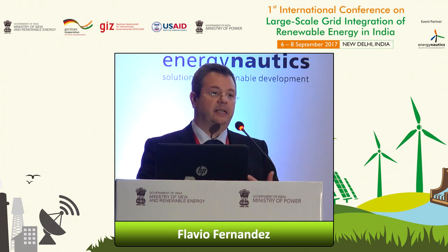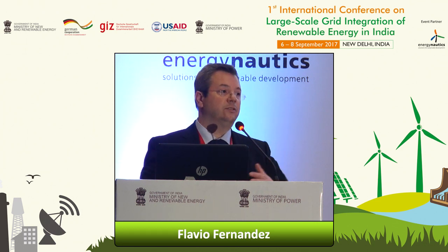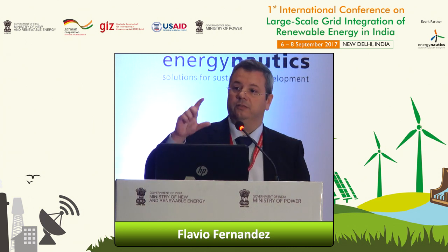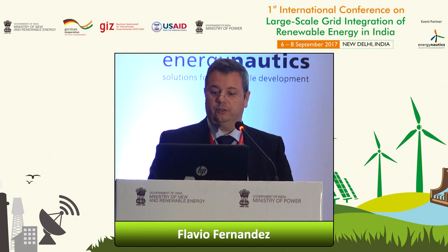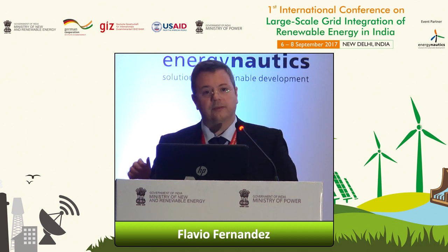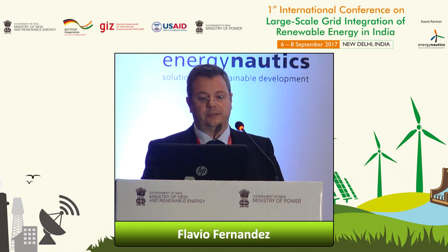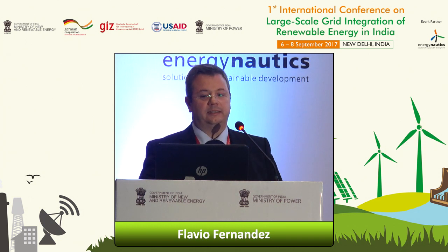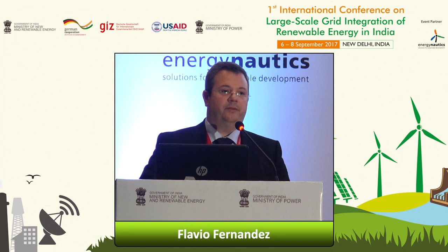For example, typical here would be the so-called K factor. That is the gain between how much current you inject depending on the voltage step. You see on the right-hand side typical simulations. The other one could be, for example, the active power frequency response, which has also been discussed here with this 50.2 Hertz effect. That you have a ramp, you ramp down the output, or for example, you may have a ramp limitation also.